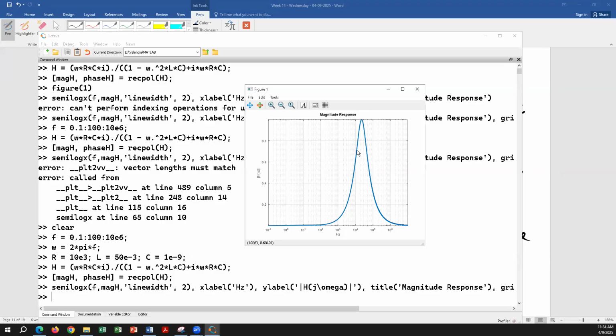Cutoff frequencies we can check from the plot, 0.7071, about 11.3K on the lower side, and 44K on the upper side. So 44 minus 11, 33K. Bandwidth is about 33 kilohertz. And again, we're going to derive those equations so we can calculate them mathematically as well. But this is your plot.